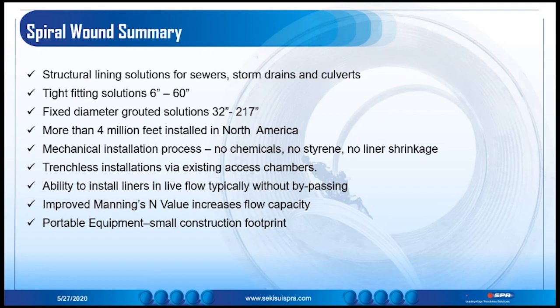Okay, thank you, Chris. Our next question is, is access okay via a 23-inch clear opening of most manhole frames? I can take that, Ryan. The answer is yes. Our machinery for our products needs only a 22-inch manhole opening. Our equipment can be disassembled and then pass through the 22-inch opening and then reassembled once it's in the access chamber. So no site excavation is required. Thank you, Jackie. Do you have to limit the grout pressures to prevent liner collapse or excessive loads? Well, Ryan, depending on the specific gravity of the grout needed in an application, we will recommend the bracing system needed to hold the liner in place and prevent it from collapsing.